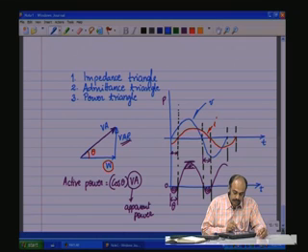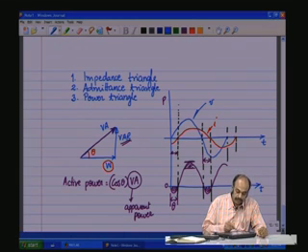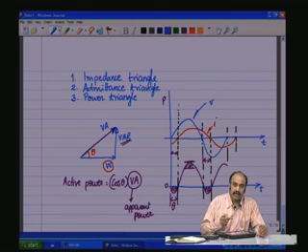So, if you want to have some active power, if cos theta is closer to 1, then VA is almost close to the active power. If cos theta is closer to 0, to get that same active power, VA has to be very high, which means the mains has to be rated that much higher.